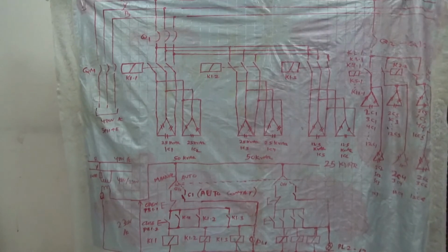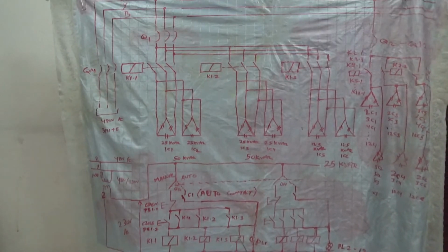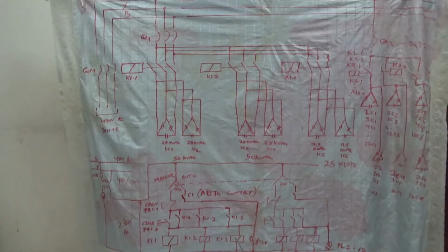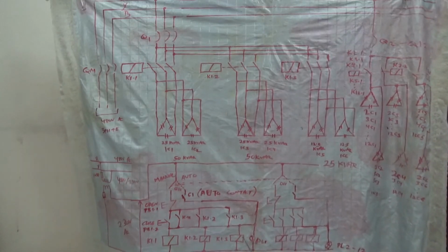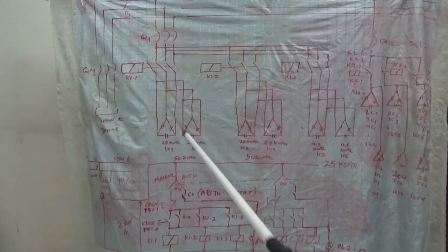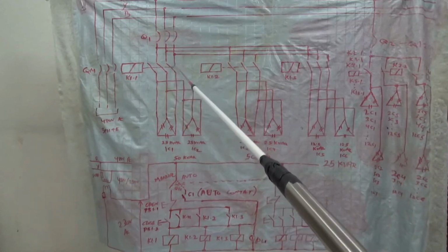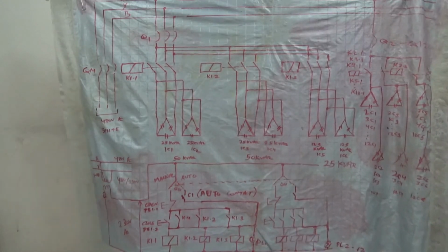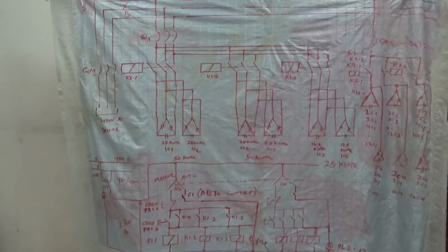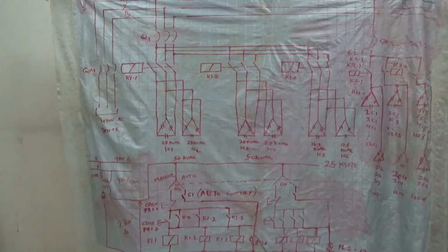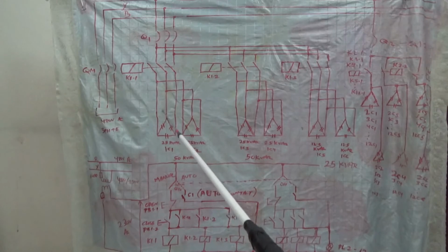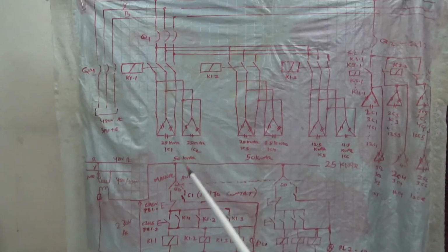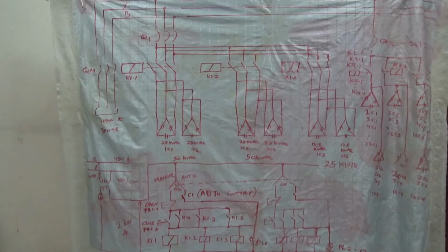The contactor is like a magnetic switch. When the coil is energized, a magnetic field forms and pulls the moving part, so the fixed part and moving part get closed here. Since there is a pilot light parallel to the coil, it gives indication that the contactor is switched on. Obviously, when the contactor is switched on, the capacitor will be charged. So when PL1 glows, it indicates that the capacitor banks are on.